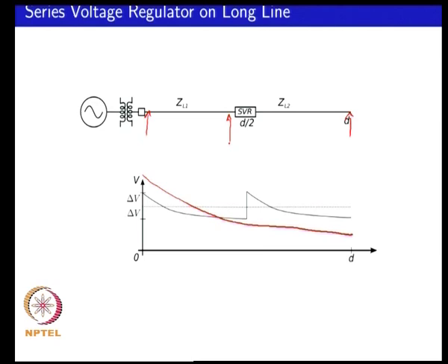So, we will look at the different possible cases, and we will see that now if we have DGs that are of reasonable size, so the power rating is of similar magnitude to the feeder power, then you could have situations where you might end up with maybe under voltage at the end of the feeder, or you might have over voltages at different locations on the feeder based on your DG connection. Okay. So, we will look at the different cases.